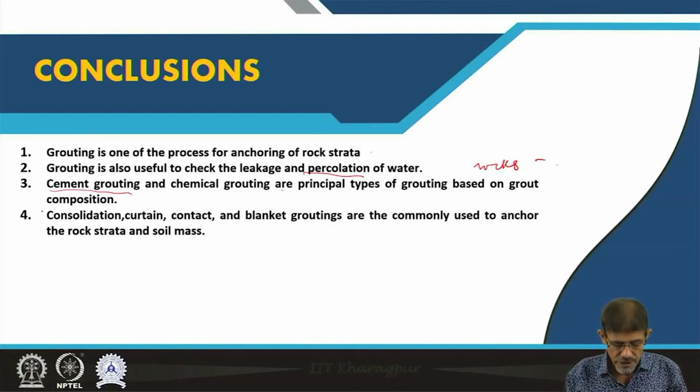Then on the basis of process, grouting can be defined as consolidation grouting, curtain grouting, contact grouting, blanket grouting and special purpose grouting. Special purpose grouting we generally do not perform in the case of anchoring of rock strata or soil layers.